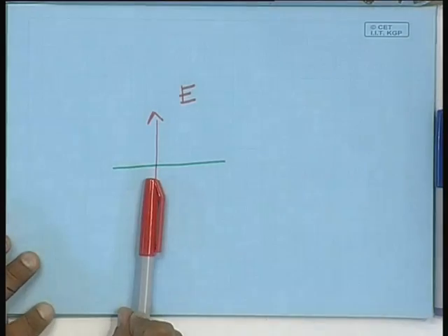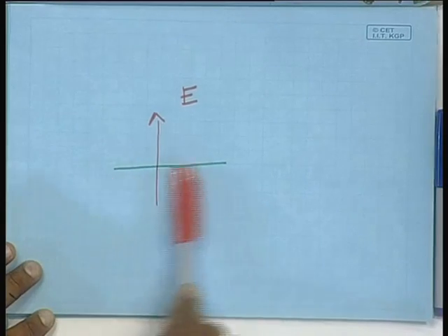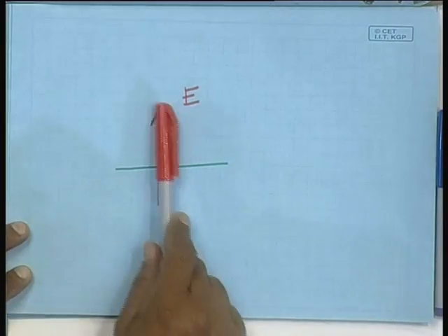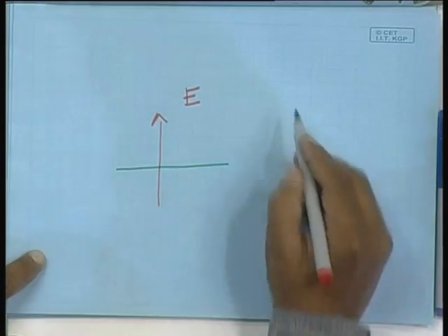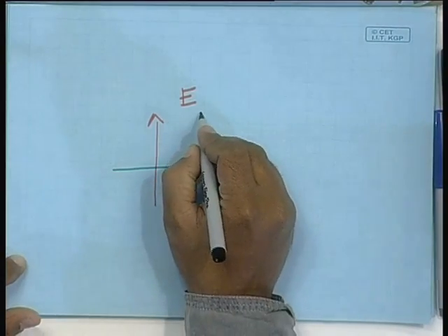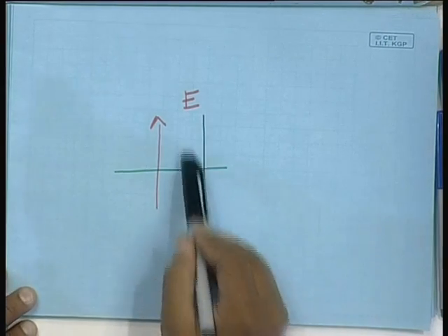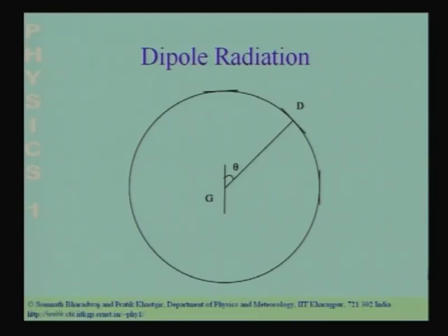Okay, so this is a point which we should bear in mind. If the metal wire AB which I am using to detect the electric field is perpendicular to the direction of the electric field, it will not experience any voltage difference and there will be no signal picked up here. Signal will be picked up only if the dipole is aligned. So, if the dipole which I am using to detect the electric field is aligned in the same direction, it is only then that a voltage difference will be produced across it and a signal picked up. So, coming back to this picture, if I were to put a dipole in the perpendicular direction here, I would get nothing.